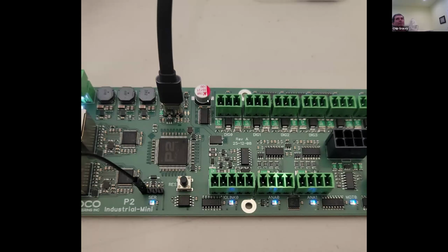So what happened was, as I was manipulating the little prober things, the little pinchers, with the power off, I didn't realize that I was shorting a 3.3-volt pin right next to one of the 24-volt supply pins. And so it not only blew out the pins on that H-bridge chip, it took out a section of 4 pins on the P2, which is a real pain.